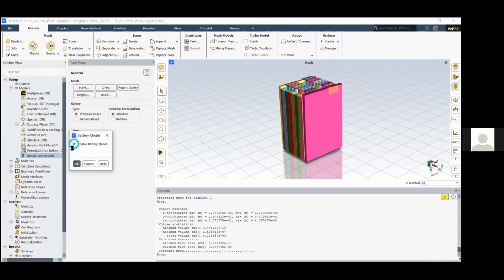According to that component size, the sizing of the elements in that particular component will be changing. So that is the reason it will create more mesh. You're using a kind of shared topology? Yes, shared topology, and you can say conformal meshing, will be used over there.